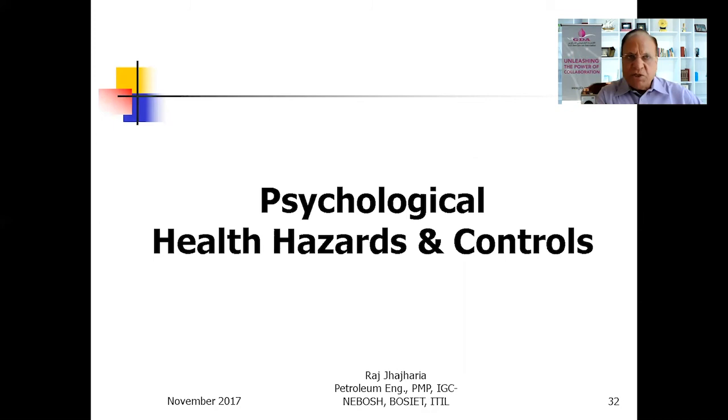But in general, the fire extinguishers have to have different types. And two things I would like to highlight, especially about the dry powder. Dry powder, normally when you are keeping it in the vertical position, settles at the bottom, and let's say more than half of the cylinder is empty, filled with air. So when the dry powder settles down and remains in that position for a long time, let's say 6 months or so, it forms a cake.